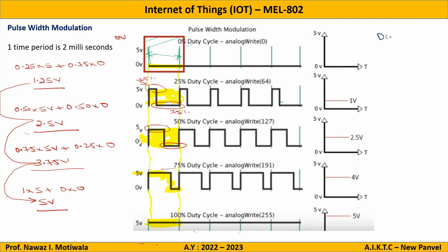So for digital inputs, there are only 2 possibilities, either 0 or 1. It will be off or it will be on. But here we need to keep it on for various intensities. So that will go into the analog part. That will not go into the digital part. Digital means only off or on. It will not go into the middle range. So here I will write analog, wherein I can use any values between 0 and 1, or any values between, let us say, 0 volts to 5 volts. So this comes under analog.